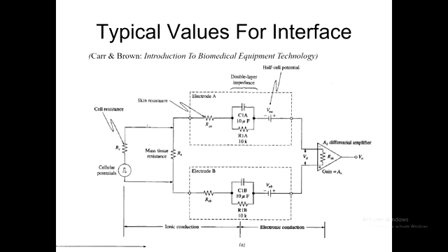Would the only frequency components be just the resistor and the capacitor? Yeah, it's in parallel. But there will be the effect of the other resistors, which you can imagine in parallel. Right? Can you find a time constant for the dead circuit, is the question. Do you understand what I mean by that?